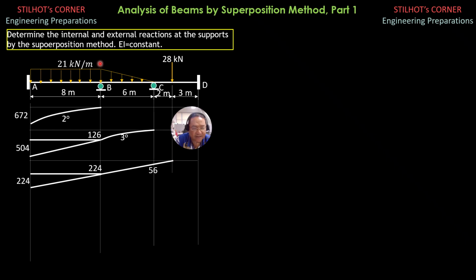Then that 126 kilonewton meter couple is constant along AB, but the 1/2 of 6 times 21, or 63 kilonewtons, times 8 is 504. Then the moment diagram by parts of this 28 kilonewton load at the fixed wall at C first, 28 times 2, so you have 56.